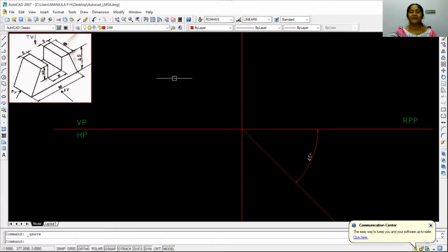So we are drawing the front view here, the top view here, and the side view of the component in this region. Since we have already drawn it in the sketchbook, what is the front view? I have to draw a trapezium of 100 and the height is 45 mm with the rectangular slot. The depth of the slot is at a distance of 25 mm from the top, and the width of the slot is 30 mm. So for that, what am I supposed to do?